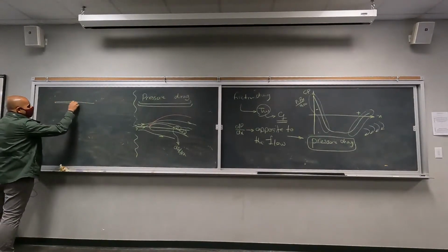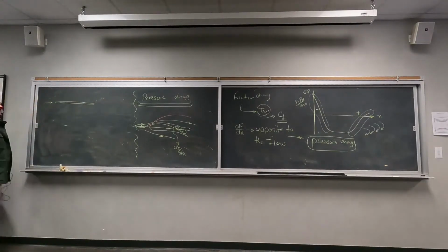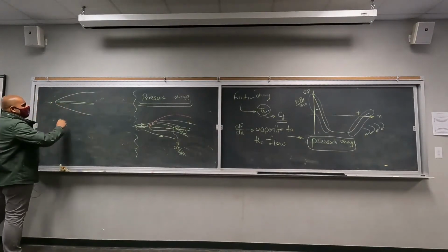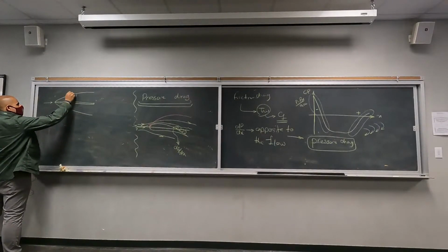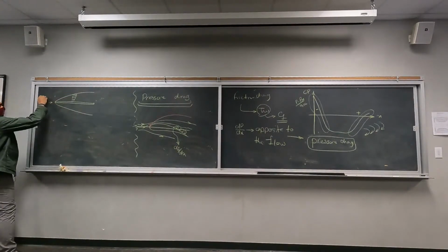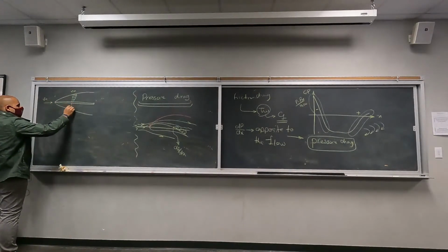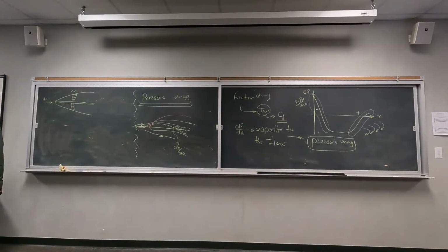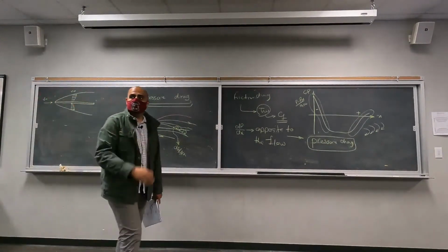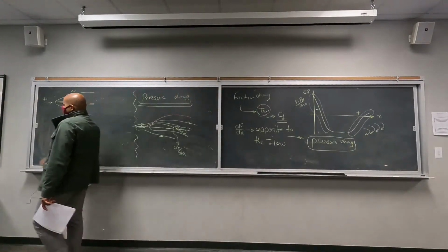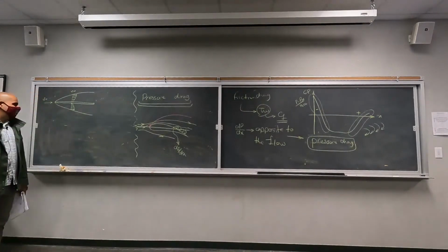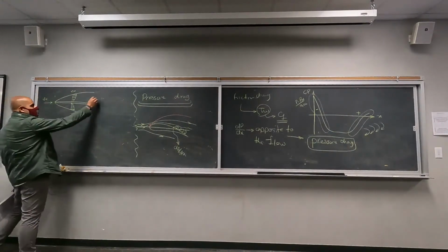Let's say we have a flat plate. It doesn't really matter what your velocity is when the flow approaches the flat plate, but you will have a region in which your velocity goes from 0 to the free stream velocity, v infinity, on both top and bottom. This effectively happens because some of the flow momentum is going to be lost because of the presence of the flat plate, right? This momentum usually dissipates as heat, or through any other kind of energy dissipation. So that is going to be the source of friction drag.